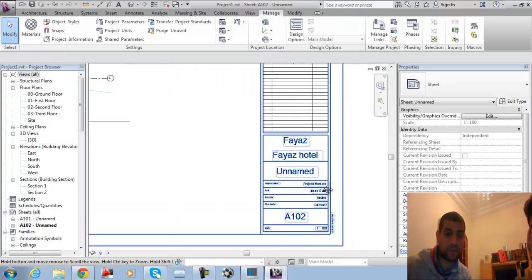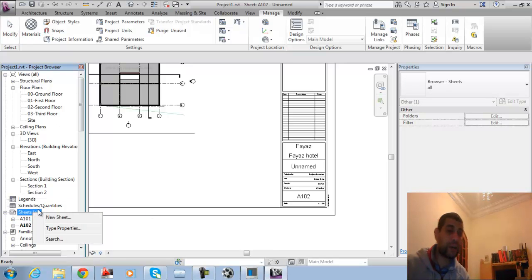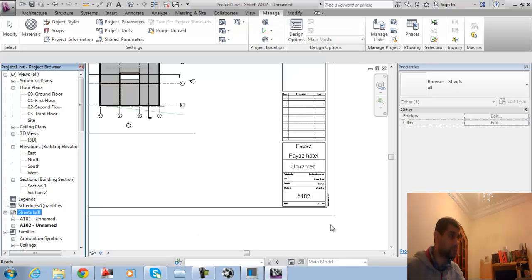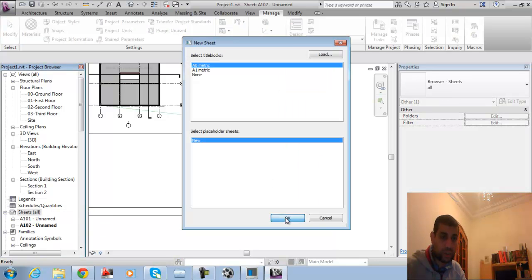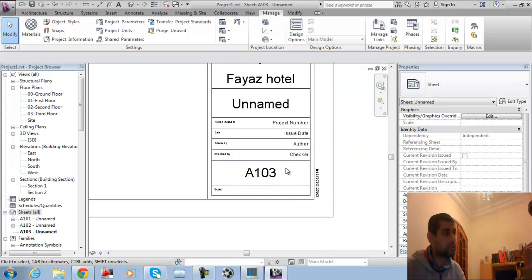Okay, and in this case, that means if you adjust all this information from project information, you can add another additional project information and additional parameters. That means this is the default parameters inside Revit, or you can add additional parameters from outside Revit to be stored in a text file, and this family can use this information to read it from outside text. Okay, as additional information. In this case, if you create your own another sheet, okay, you'll see this information already read.